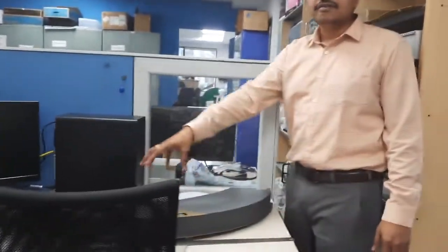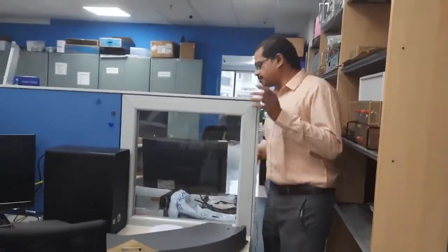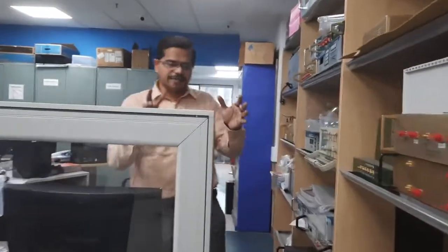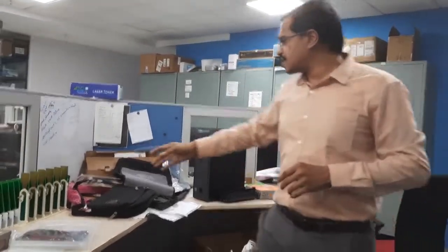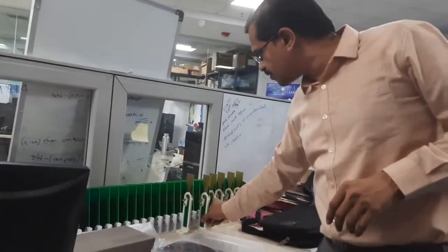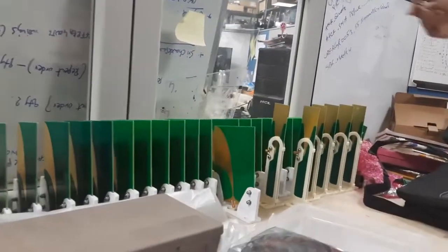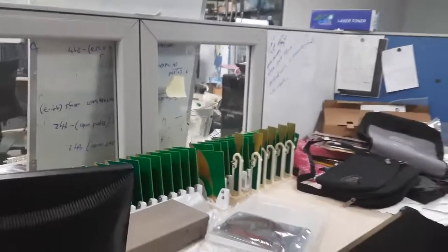We also deal with RF absorbing material. RF absorbers are very crucial, because in an antenna system, when you are running precise algorithms with amplitude, phase and time delay, it is important that you control the multipath at least within your system. You can't control the multipath outside, and the multipath coming from outside we deal with at the algorithm level. These are the set of antenna arrays which are getting ready for assembly. These are for the lower frequency band, and these are the broadband ones for the higher frequency band. These antenna arrays we assemble in our antenna system.